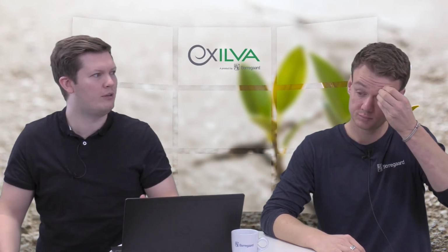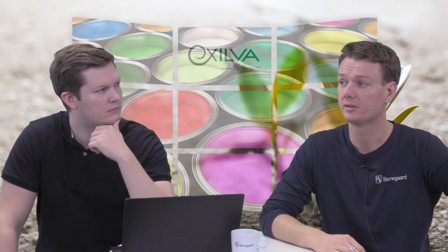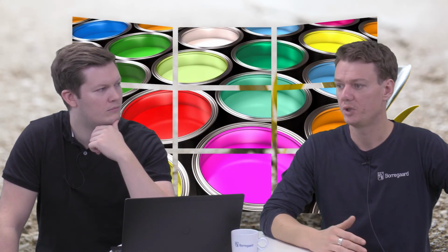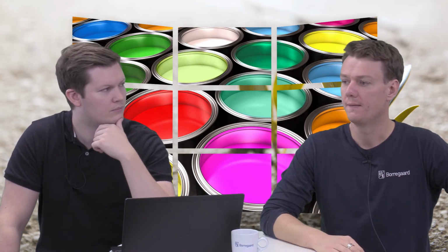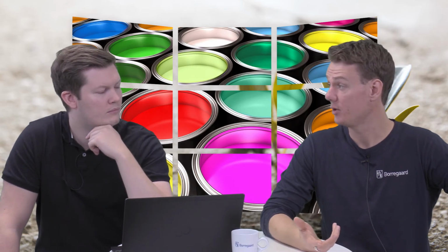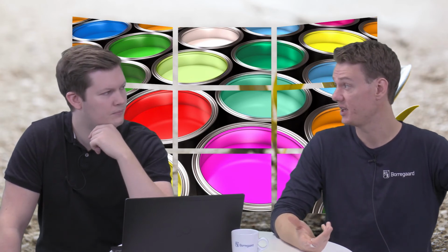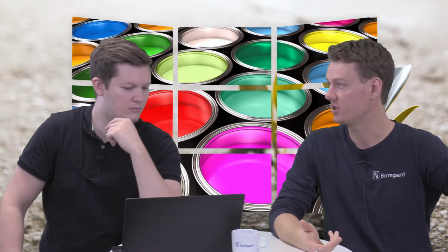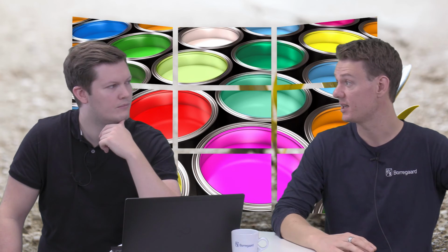And if we're talking final product here, what effect is this going to have on the final tinted coating? Yeah, so for the end user, things you want when you're painting, you want good sag resistance. It's not going to drip off the surface. You want to add fewer coats onto the wall, for example. So you want thicker brush loading, and you could possibly get that, and also in-can stability. So stability over time. You're not going to get a nasty water layer when you open the can after 3 or 4 months, so it's going to be quite stable. And you can also spray if you want, because it's very shear thinning. So that also adds added benefits there.